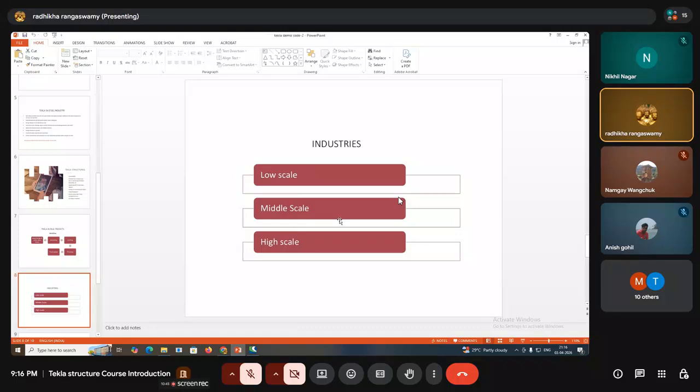LOD is about, if you are having a project, say a steel project, for example, about 5,000 tonnes of steel is going to be implemented in that structure. So you have to know the data, right? For column, how many tonnes it is coming. For beam, how many tonnes it is coming. And what is the profile name? And what are the connecting plates coming there? And what is the thickness of it? And what is the pitch distance while we are connecting with the bolts? So all the complete data will be easily provided when we work with this.